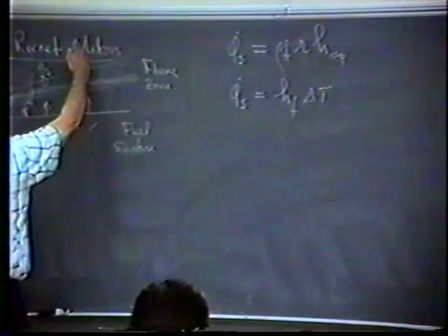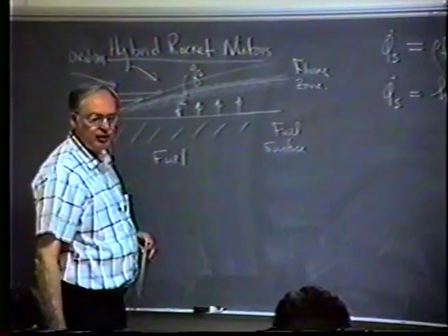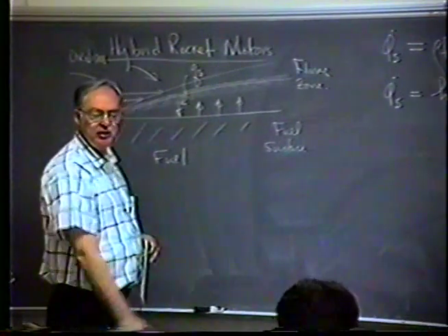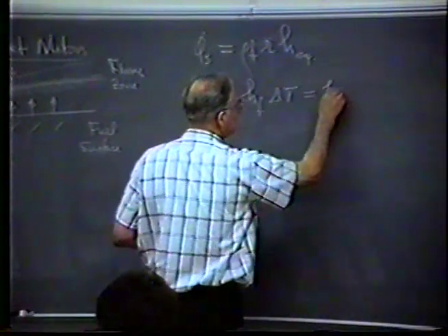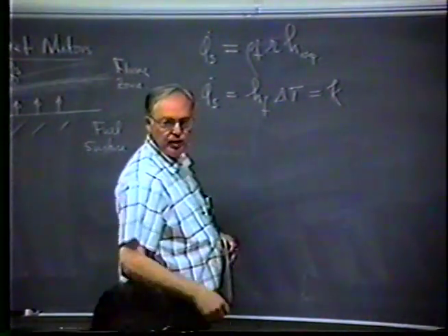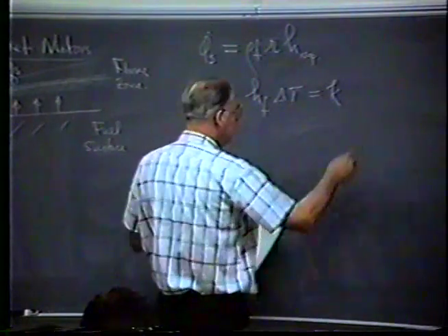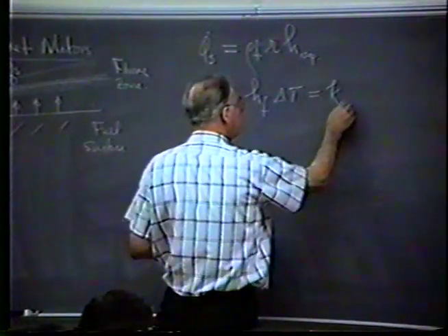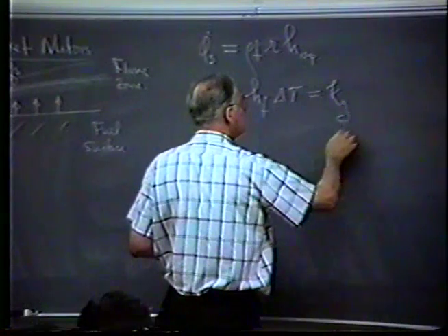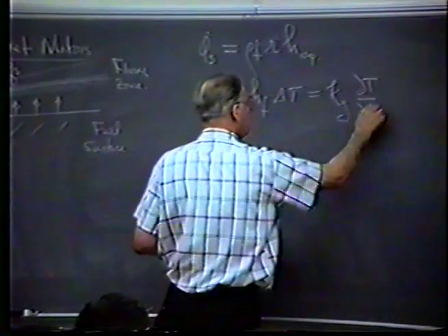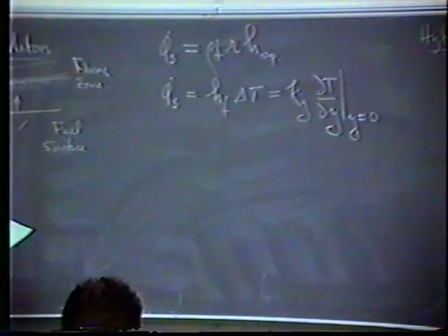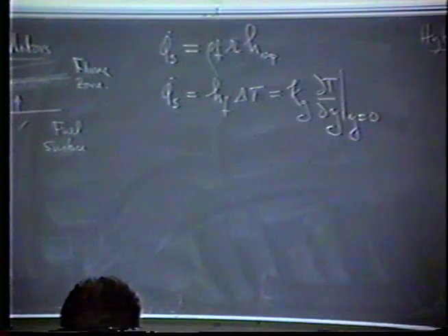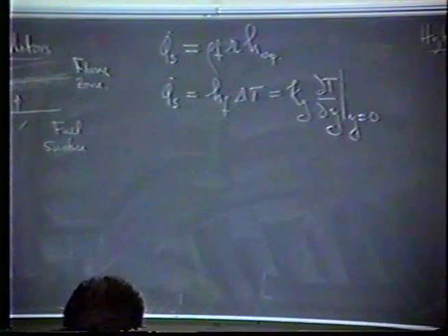All right, now when you have heat transfer across the boundary layer by so-called convective means, where does that heat transfer go? Well, it goes into the surface, and so that goes into a heat transfer term that involves thermal conductivity of the gaseous phase, times the gradient in the temperature at the surface. Does that make sense? K of G is the thermal conductivity of the gas at the surface.